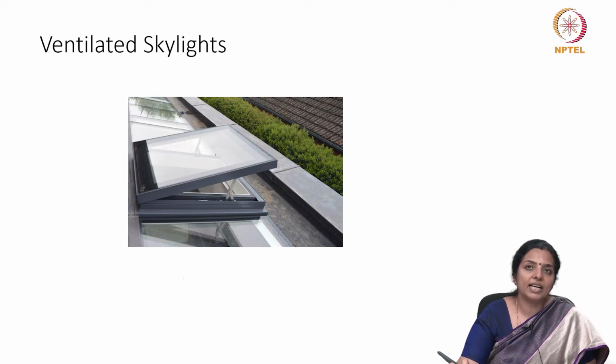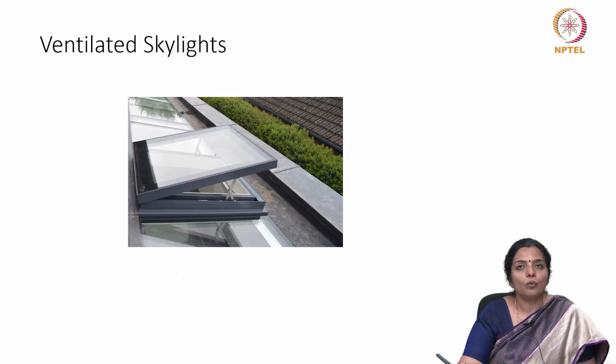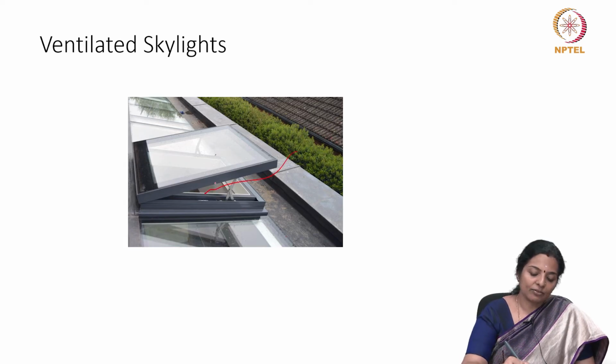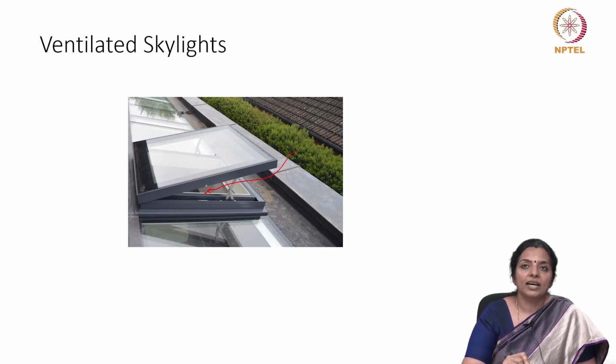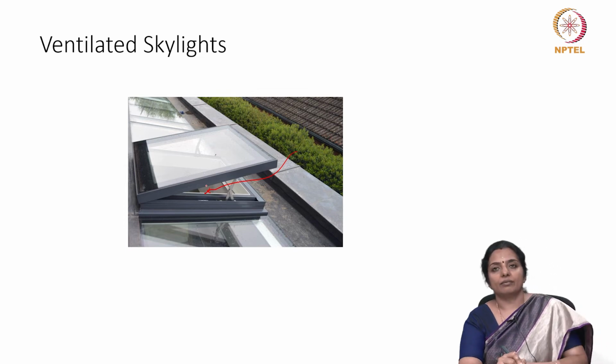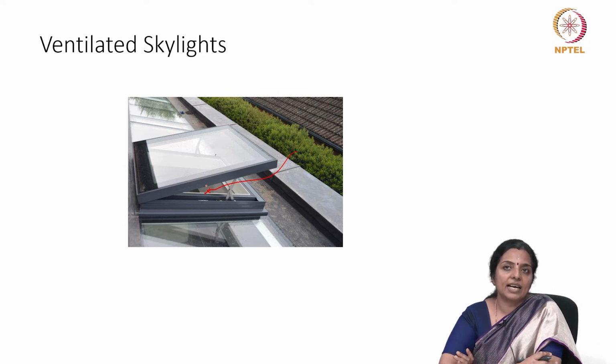Next is you have ventilated skylights. If you want daylight in your room but would like air as well, we can have ventilated skylights. They look exactly like fixed skylights, but we can open them in and let in some fresh air inside and remove excess moisture. Ventilated skylights are good for kitchens, bathrooms and living rooms. There must be a source of access to operate these skylights.